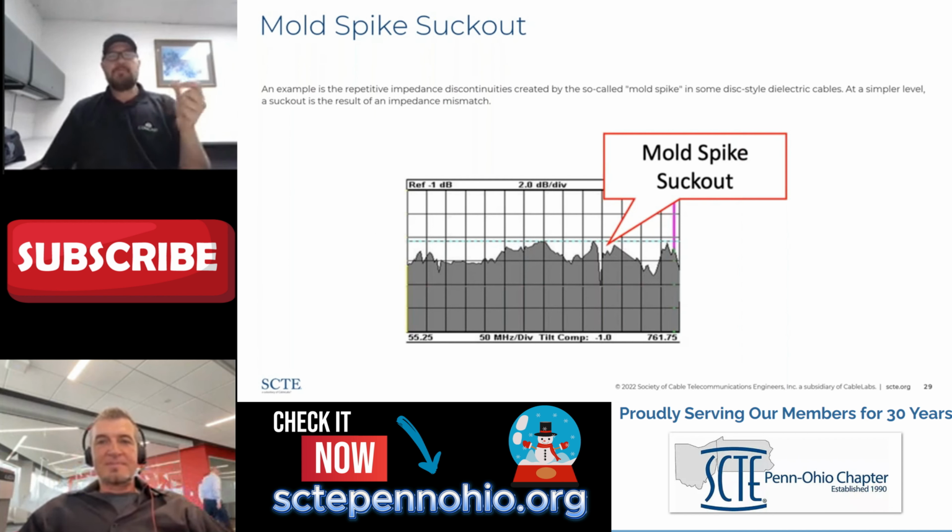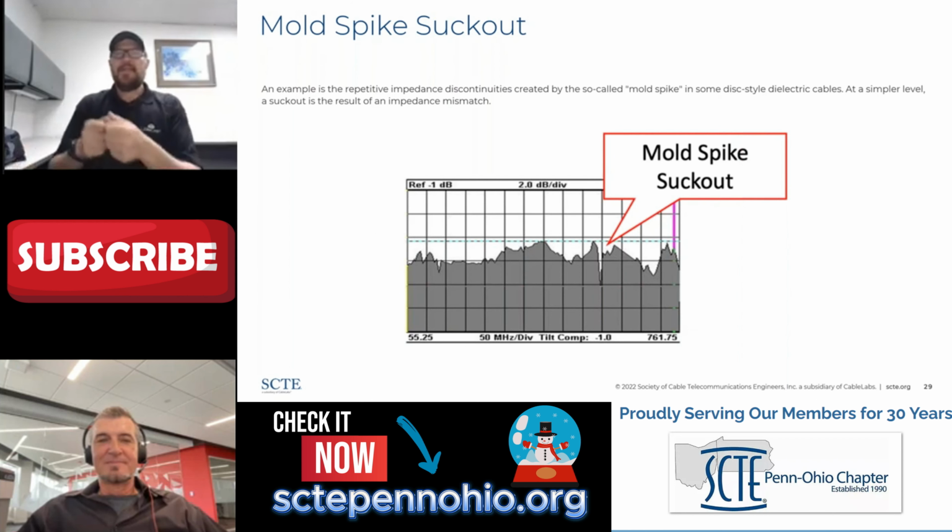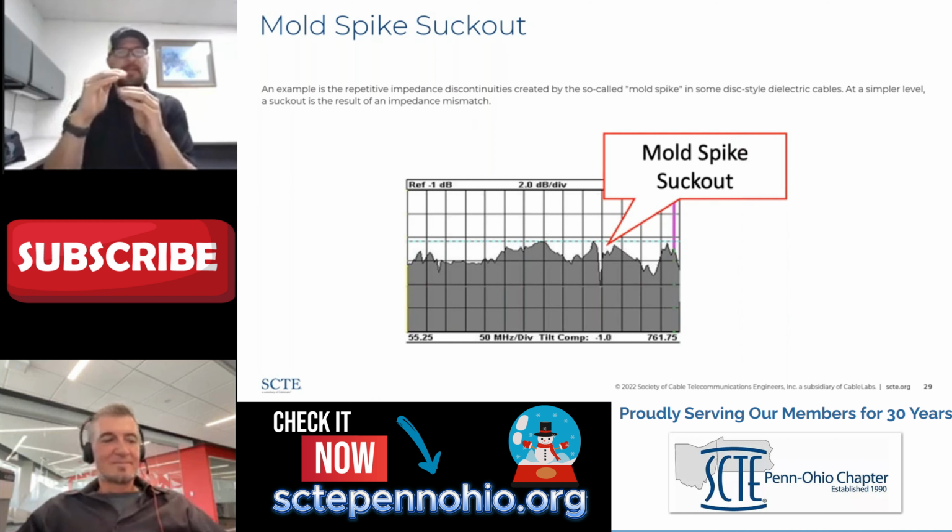So you take your cable grips and you install them every 18 inches precisely all the way around that house, and then you zip tie the cable to those cable attachments. And every time you put a zip tie around that drop cable, you squeeze the cable just slightly. And that creates a small impedance mismatch because you change the ratio of the distance between the outer conductor, which in this case is braid, to the center conductor.